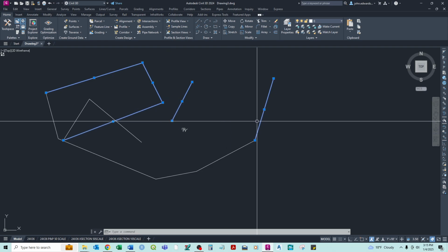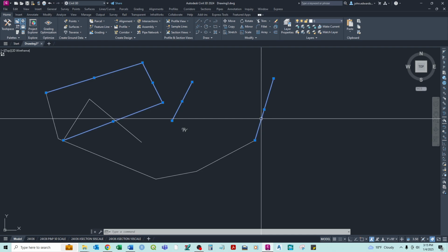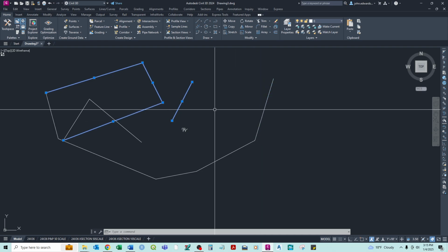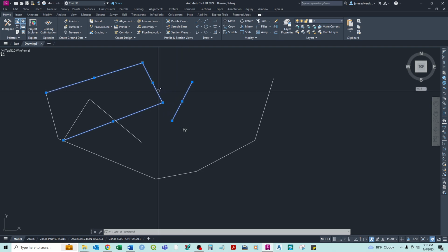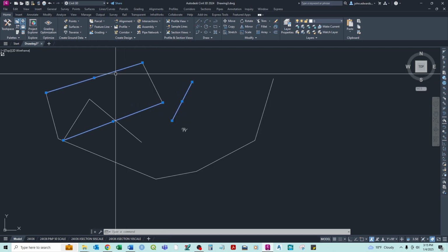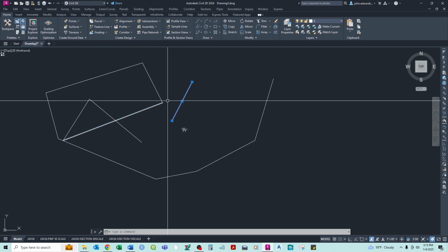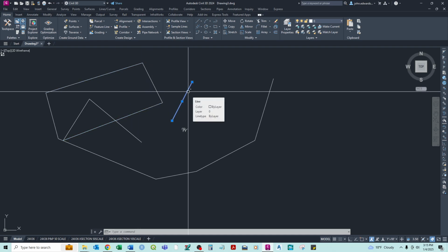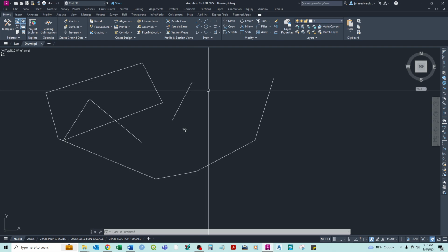But how do you unpick? You can't just re-click to unpick. Now you can hit Shift and click to reduce the selection. So if you hold down Shift, you notice now when we hover over, I'm holding down Shift right now, and you see there's a little negative or minus symbol over that thing. And if I click it, it takes that out of the selection. So I can actually deselect everything by holding down Shift and selecting it again. Okay.